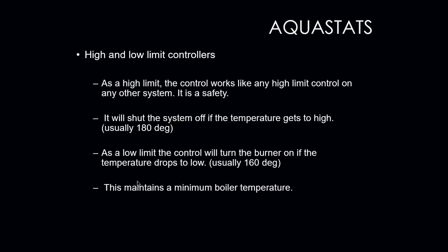Aquastats. Aquastats are commonly found on boilers. They could be either on an oil-fired boiler or a gas-fired boiler. They are the main component in the system that's going to control the water temperature of that boiler. Okay, just as the name states, aquastat. Aqua, water, stat, temperature. So your aquastats are going to have a high and a low limit to them.